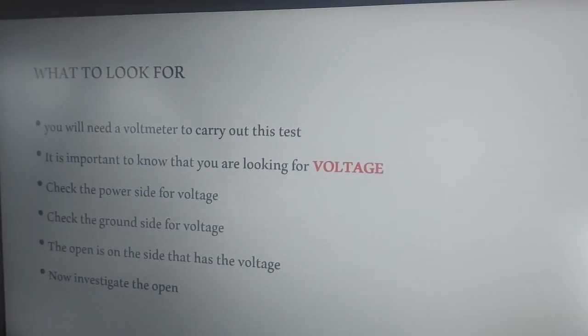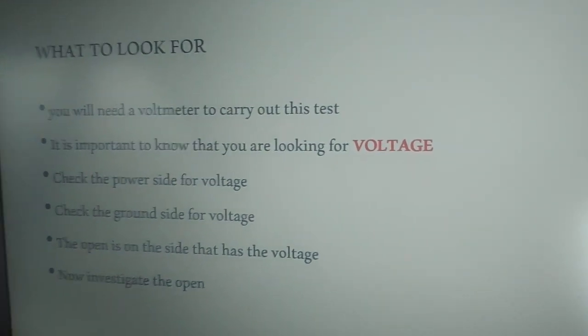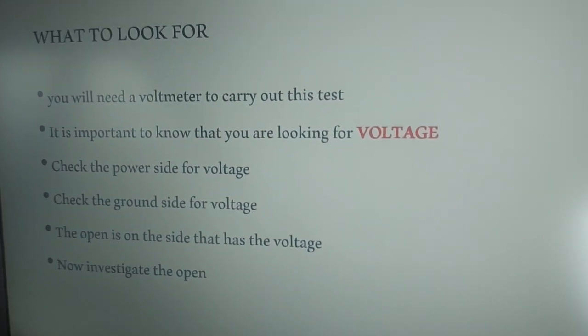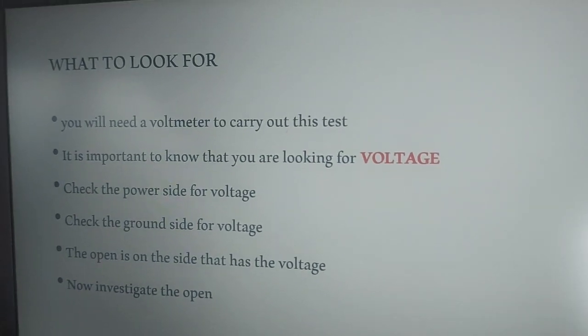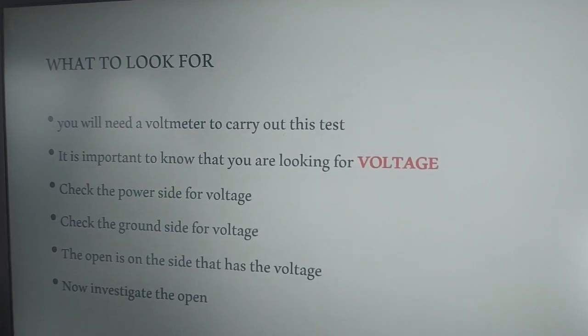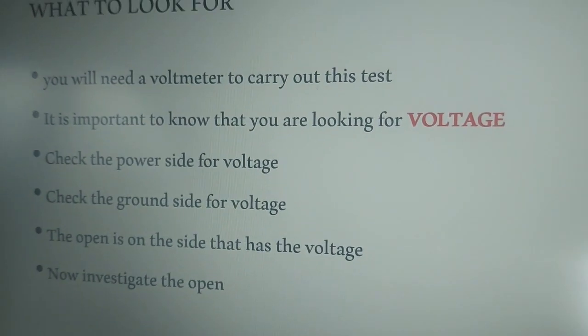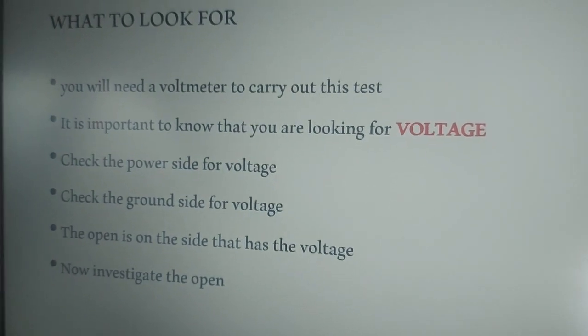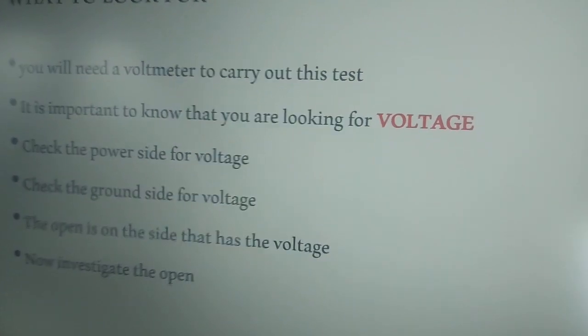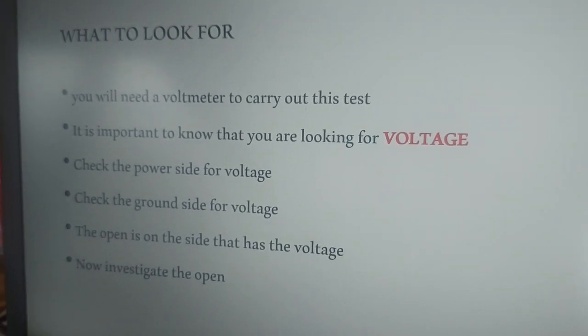On the slide, we are saying then, check the power side for voltage. So you check on the power side, which I'm going to demonstrate. If you can't find any voltage on the power side, you need then to go to the ground side and check for power there.